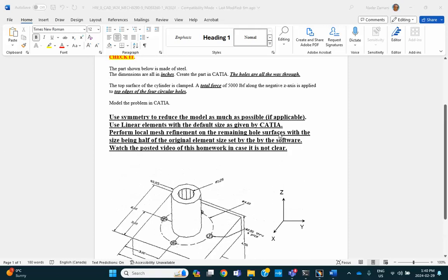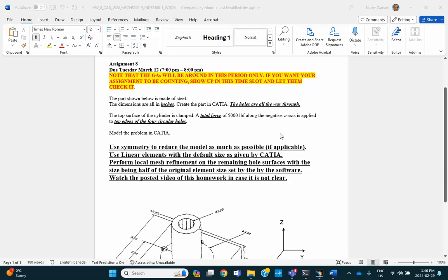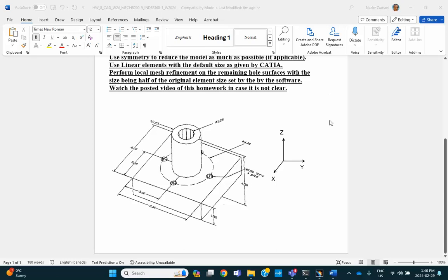Okay, anything else here we have to know? No, let's move on. Oh, by the way, because you know what you're dealing with, 1/8 of this model, you have two choices. Make the 1/8 of the model, that's one option, or make the whole model and then cut it with the appropriate planes to recover that 1/8 of the structure.